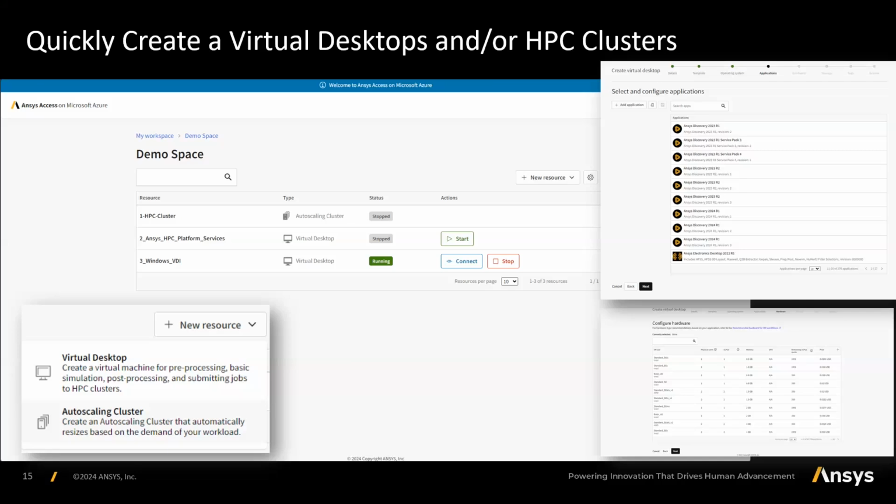So you submit a mechanical job into the HPC cluster. The head node will effectively power up the nodes for the job to run on, and the job will solve. And as soon as the job's finished, the data will be saved and the compute nodes will be powered down. So you're getting a really good cost efficiency here, because the compute nodes are only up when they're needed. And that means the cluster auto scales depending on the workload that's coming in.